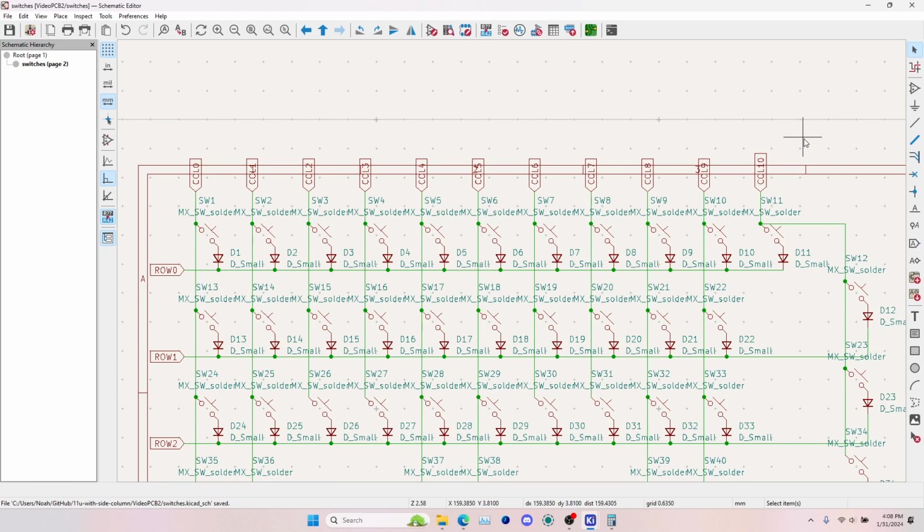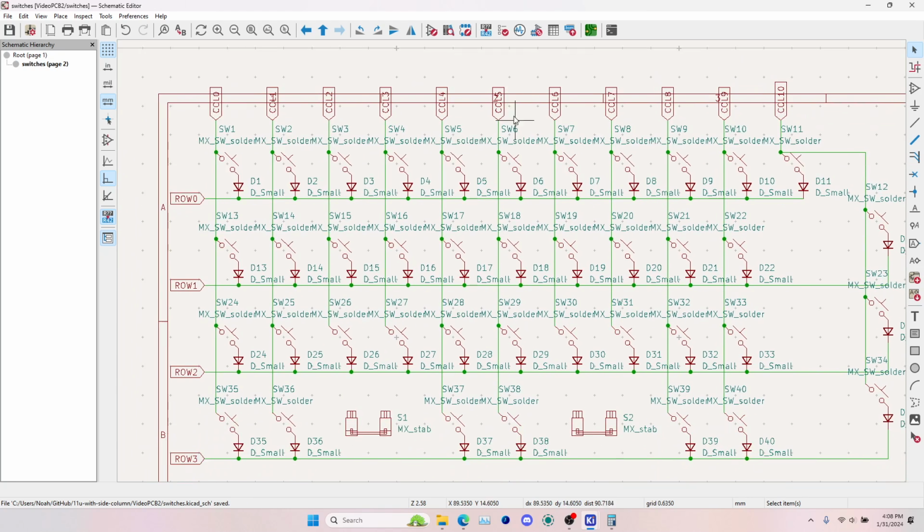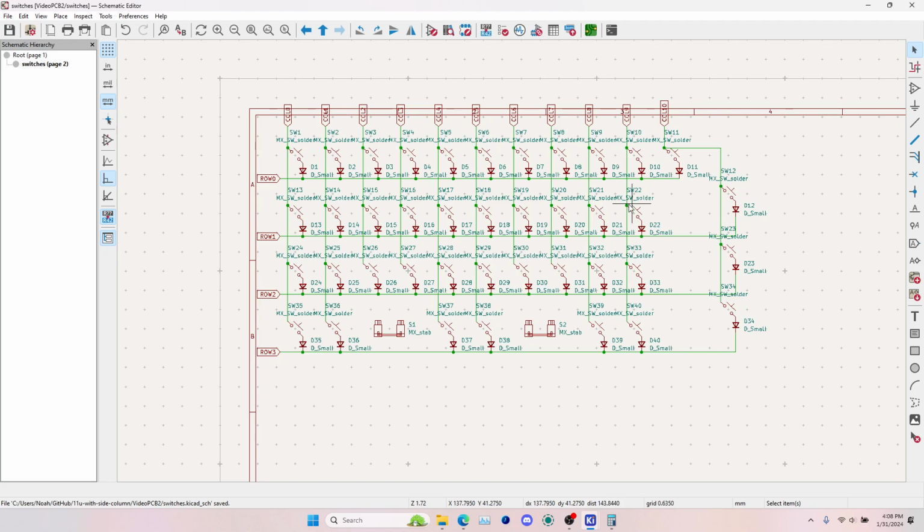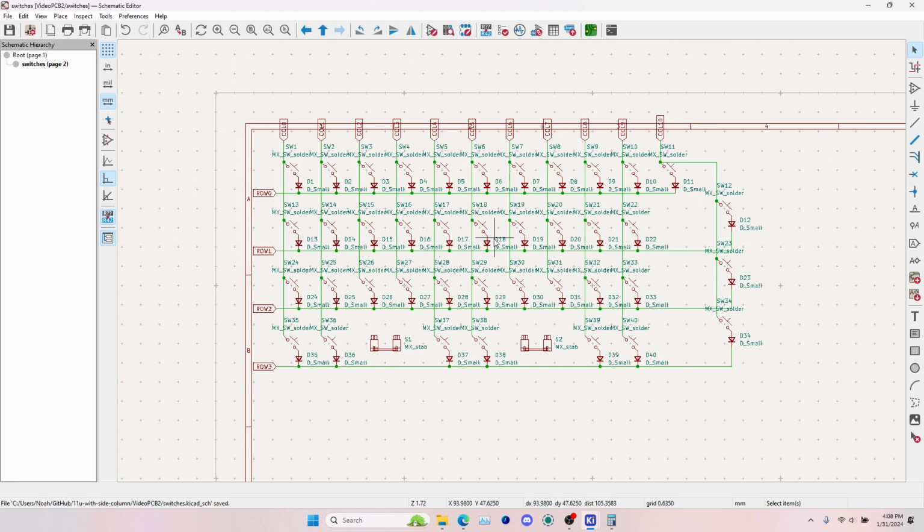So 5 and 9, so 10 and 9 is 19. So 23 down to 19 pins. You saved 4 pins there, and that's enough pins to add like RGB and an encoder. So that's enough pins to add like an OLED and a knob, right? When you're struggling for pins, you can always rearrange the matrix electrically, but keep the layout the same physically. That's what I'm trying to say.